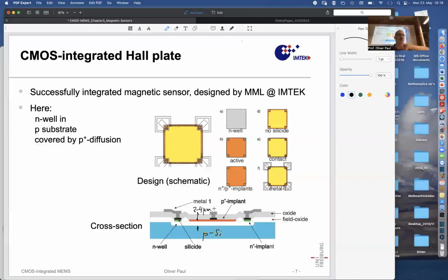So if we would like to design a Hall sensor in a CMOS technology, you have to look out for high voltage options. And that may cost a little bit more, but at least you'll be able to do that sensor. And remember, in the example of Austria Mikrosysteme or the other fab, X-FAB, they had these high voltage options. So they can do that. And sure enough, Micronas must have that too.